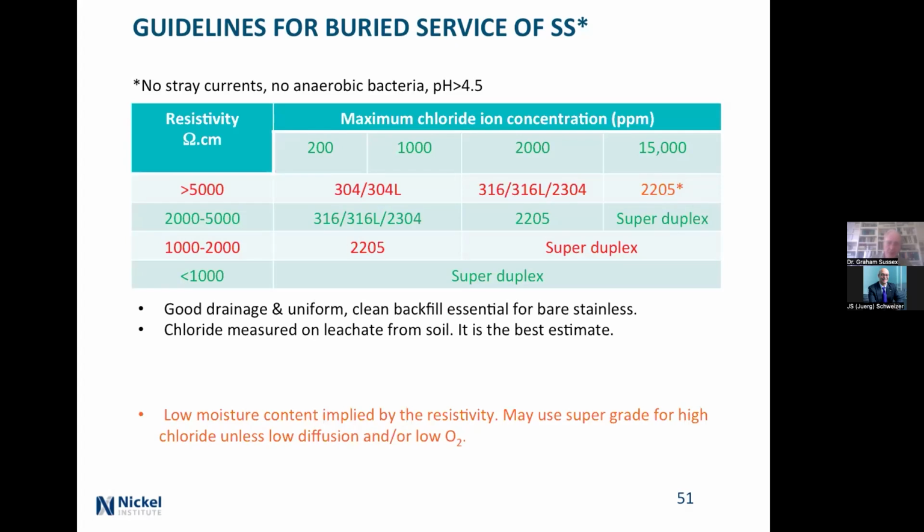Basically, you need good drainage and uniform, clean backfill. If you put a pipe down in the ground, you don't backfill it with the stuff that's around it. You use uniform backfill and compact it. And chlorides across the top, but they're measured by leaching the soil. That's the Australian standard, it's the American standard. It's the best estimate you can get.